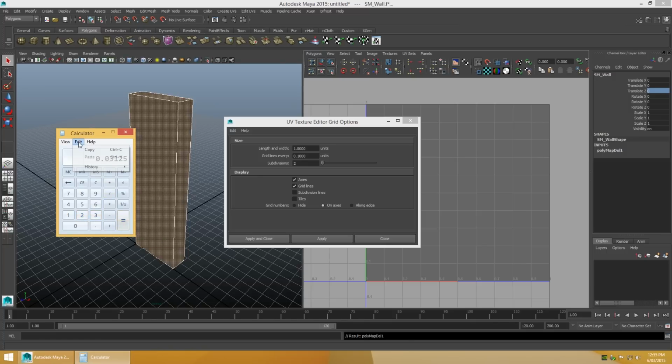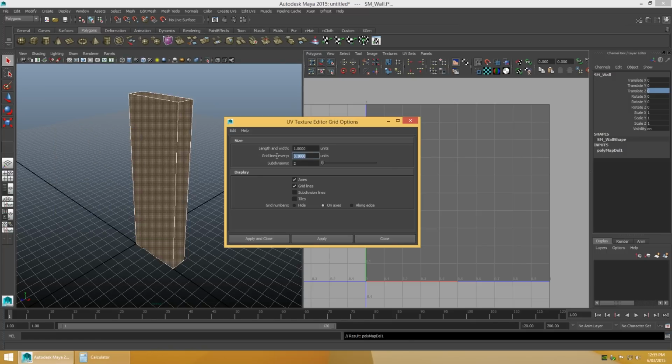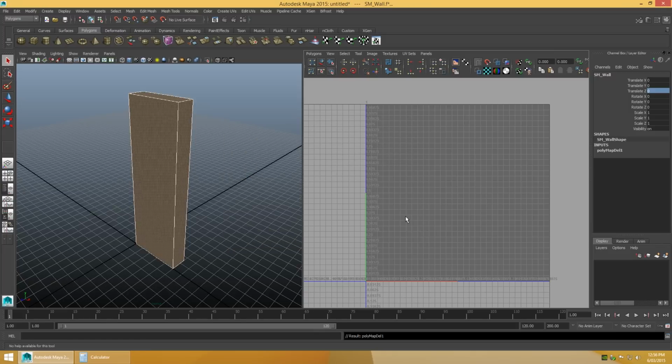So does this mean that I'll be using a Lightmap resolution of 32 within the Unreal Engine? Well, not necessarily, but it's a better idea to target a smaller Lightmap resolution than what you think is required, as it will gracefully scale upwards, whereas the same can't be said for scaling downwards, which will likely cause issues with light and shadow bleeding.